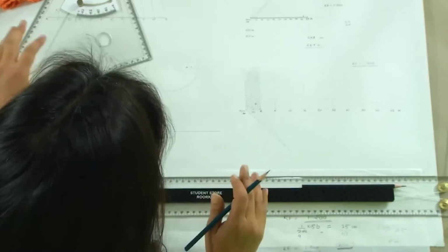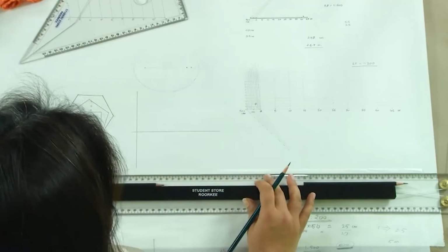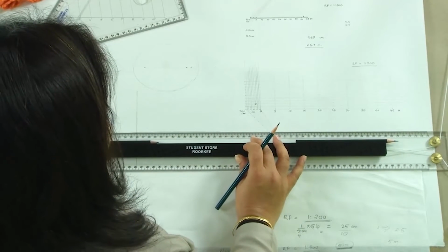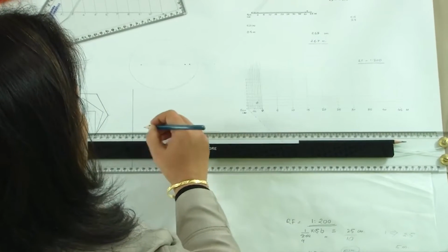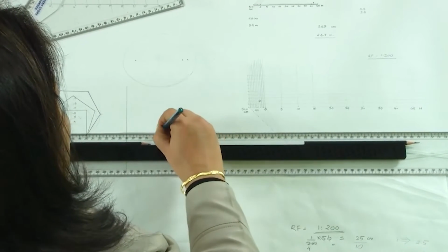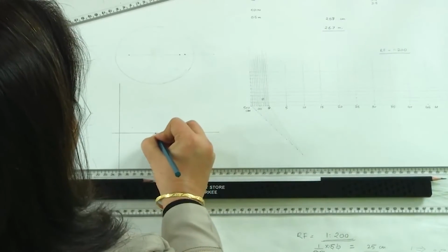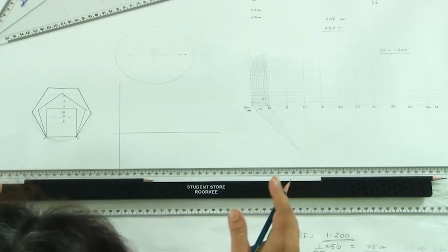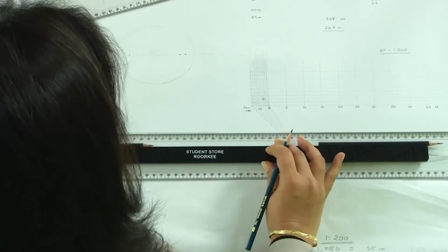So, what we would know is the distance of the focal point from the directrix. So, for example, our focal point is at a distance of 50 mm, that is 5 centimeter from the directrix. So, we know that this is focal point, and say the eccentricity of this ellipse is 2:3.